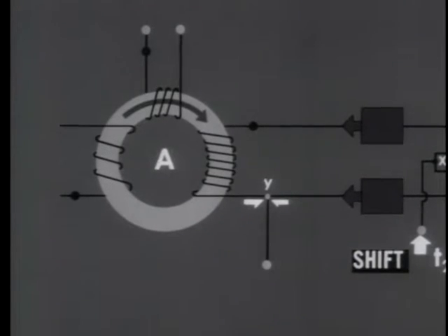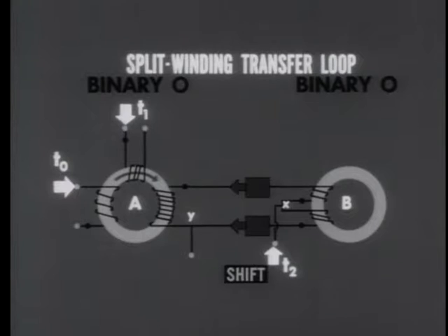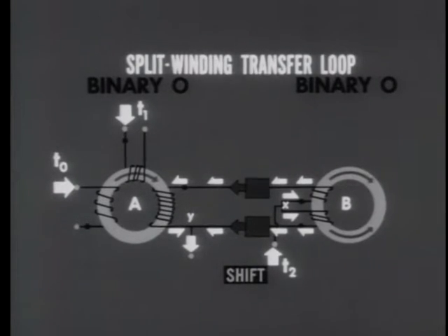At point Y, this upper branch current joins the lower branch and flows out of the loop. The result is no change in either core. Core A remains at 0 because the upper branch current is applied to its winding as a dot pulse. The upper and lower branch currents are equal, and therefore core B also remains at 0, because equal currents there produce opposing but equal magnetic fluxes, which cancel out.